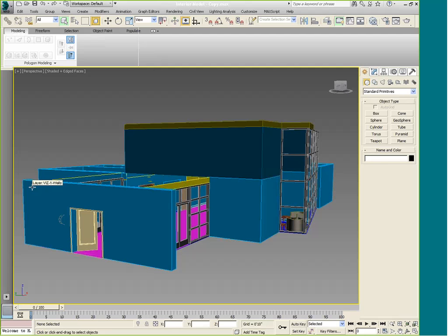Now, if I select this wall, like here, I select it, and you can see the white bounding box. The white bounding box is around the complete wall, which means that this wall is a single element or a single piece of geometry. And we will be assigning the sub-materials to different faces or different polygons of this wall. Now let's start by creating the multi-sub-object material.